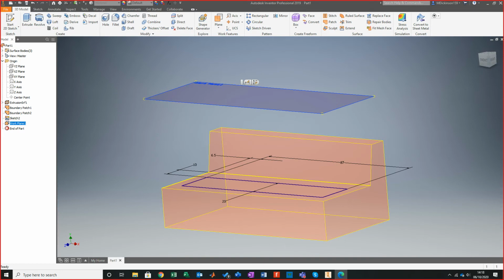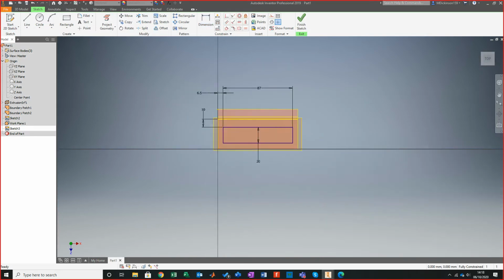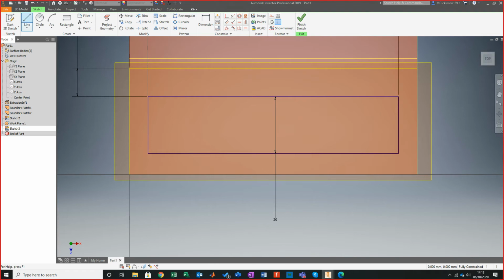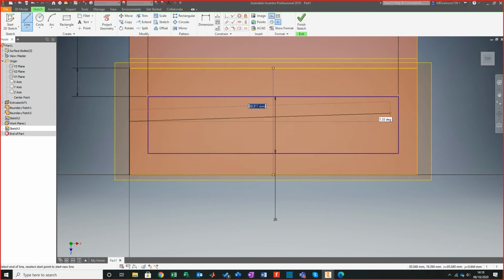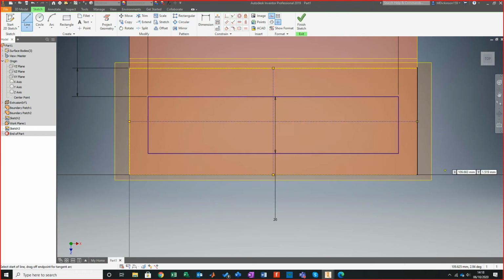So I'm on the top plane that I've just added, and I'm going to add a sketch. And what I'll do from there is go a line, construction line, tracking it to that edge there. I'm going to bring it up to that point there for interface, and then do the same thing on this side to track to that edge, and then bring it to there. So I'm giving it that crosshairs, if you will. Then I'm going to bring in a corner rectangle, and I don't want this to track to anything, so be careful about automatic tracking. Now when I say that, if I bring that over, you'll see that the line wants to locate itself. So I want to make sure that it's roughly...